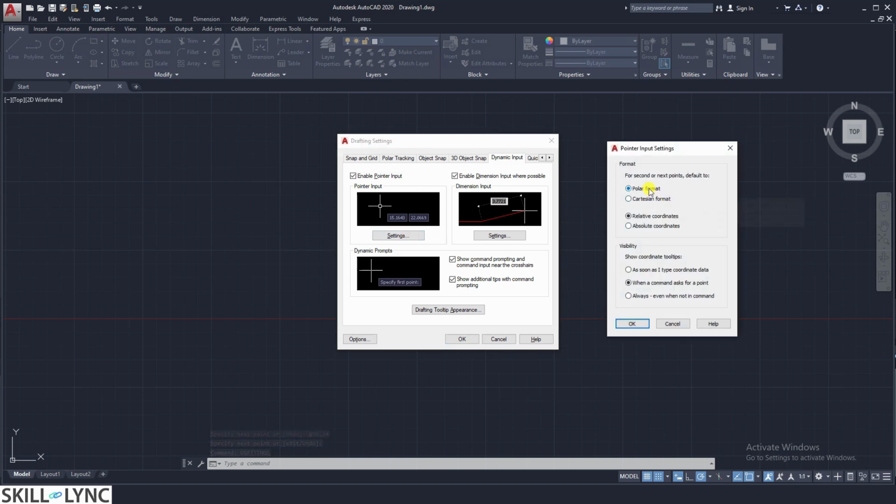So even though the default is here on the dynamic input screen, we are moving over to the default setting by forcing it using comma or angle symbol. So the same happens when we switch over from the relative coordinates to the absolute and vice versa. So relative coordinates is being used with the @ symbol, and if you want to revert back to the absolute coordinate, you can enter by the pound sign. So this is how you interchange from one dynamic input setting to the other when drafting.